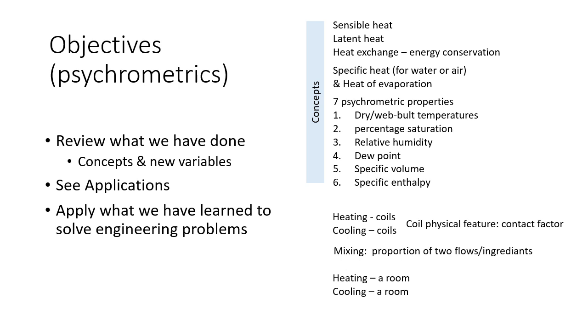If we do not remove that heat, the temperature in the room will rise, and then we'll start to feel discomfort. To avoid the temperature rise and heat accumulation, we supply cool air lower than the room temperature. So the air goes into the room and rises to the room temperature. That is the process of absorbing heat in the room.